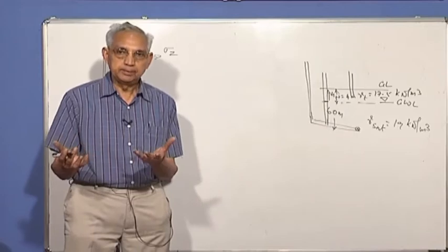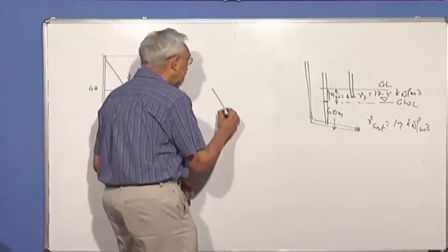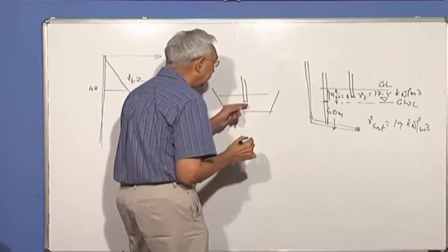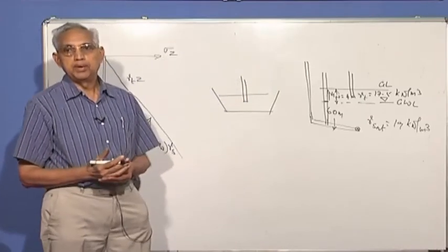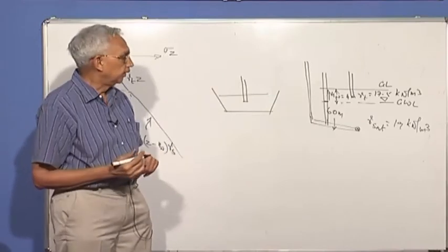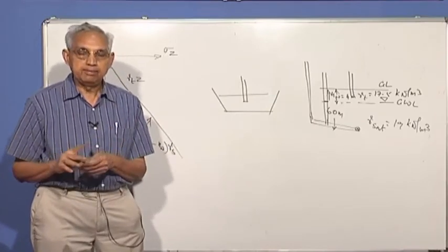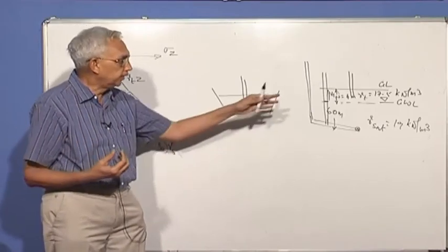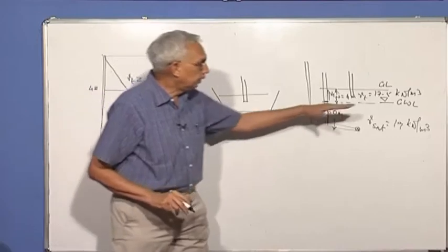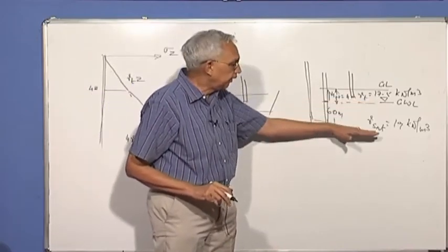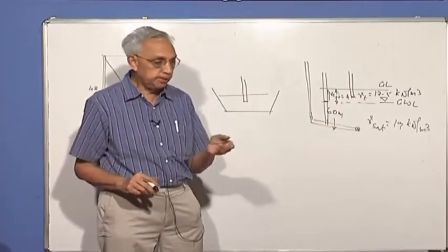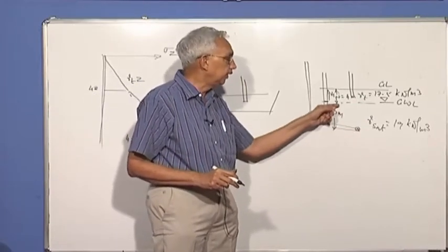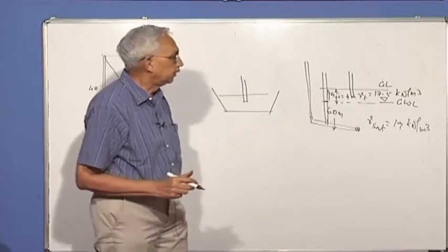It's a simple concept: if I have a bucket of water, the water pressure is a function of the depth of the point you are measuring from the top of the level. You agree that soils have interconnected voids, so the water is continuously connected to the groundwater. The water pressure here is atmospheric. We are now only talking with respect to the atmospheric pressure, so you find that the water level in the tube will rise up to groundwater level.